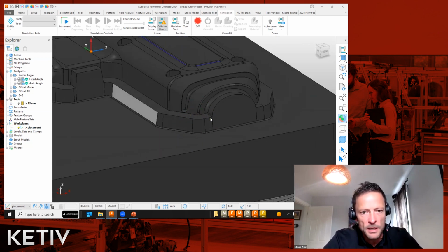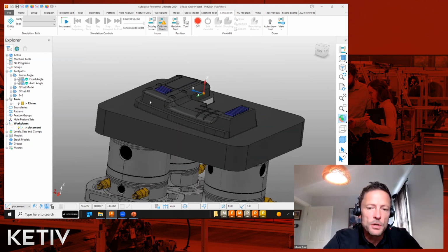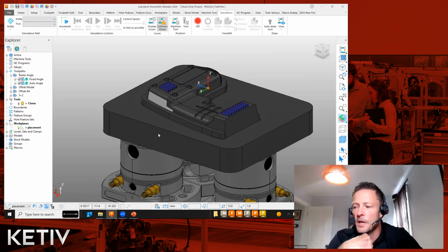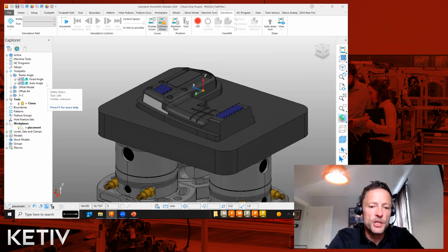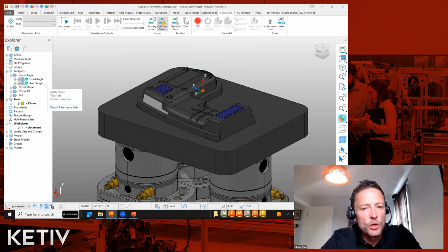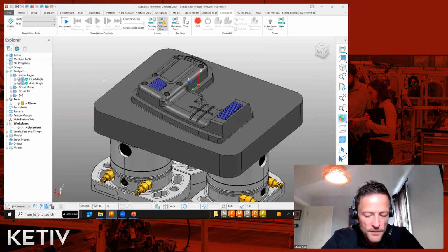But these ones here, I could machine if it's flat, of course, with a flat profiled tool. So you could just go ahead and set PowerMill off, and it will find all of those flat areas and produce some kind of 3+2 5-axis toolpath. But this addition has given us a bit more control. It's a filtering tool. A lot of other toolpaths have filtering for fragmented bits of toolpath, but this allows us to really keep it away from, in this case, a small detailed area.